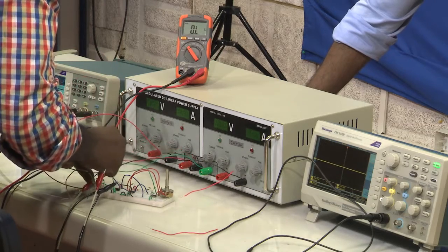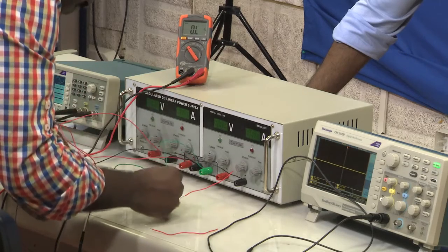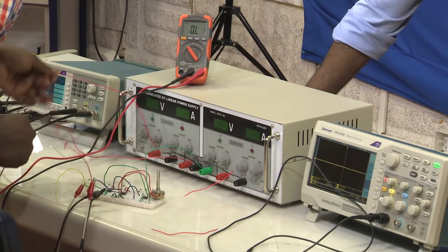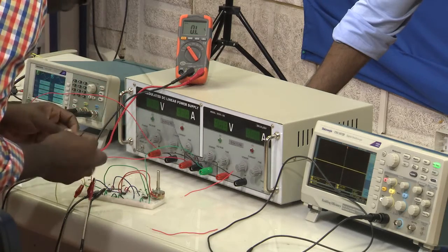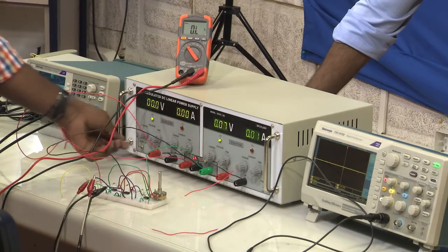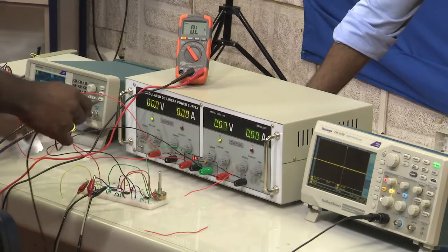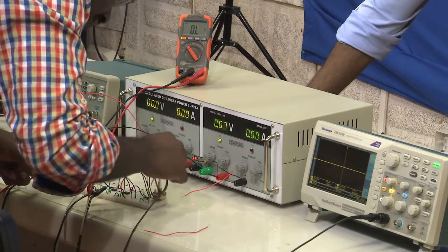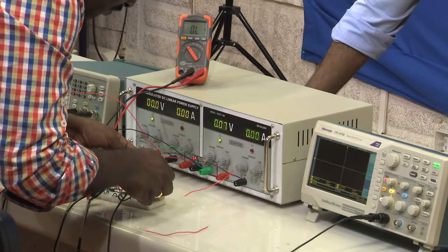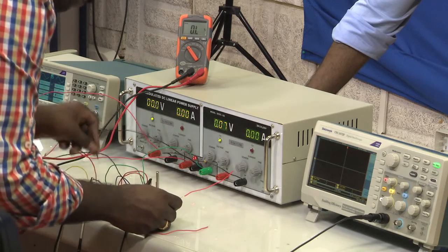Do not forget to apply the bias voltage to the operational amplifier circuits. So, we have to apply plus 15, minus 15, right. Okay. Ground to ground, alright. Turn on the DC power supply, yes, plus 15 minus 15 is given. Now, he is connecting the output of the instrumentation amplifier to the oscilloscope, and once he connects it, we can see the output of the instrumentation amplifier on the oscilloscope, alright. So, ground he needs to connect it.